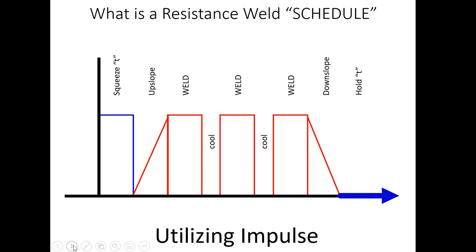Now, here's an example of a resistance weld schedule that was done specifically to try to get a softer effect around the welds. This would be typical of one that I would set up if I knew I was going to be welding boron steel, or hot stamped as it's usually called. Boron enriched materials tend to get really hard right around the weld zone. Sometimes we even weld them twice with MIG welding, applying something called a tempering bead. The extra heat actually softens the material around it and prepares it for welding.